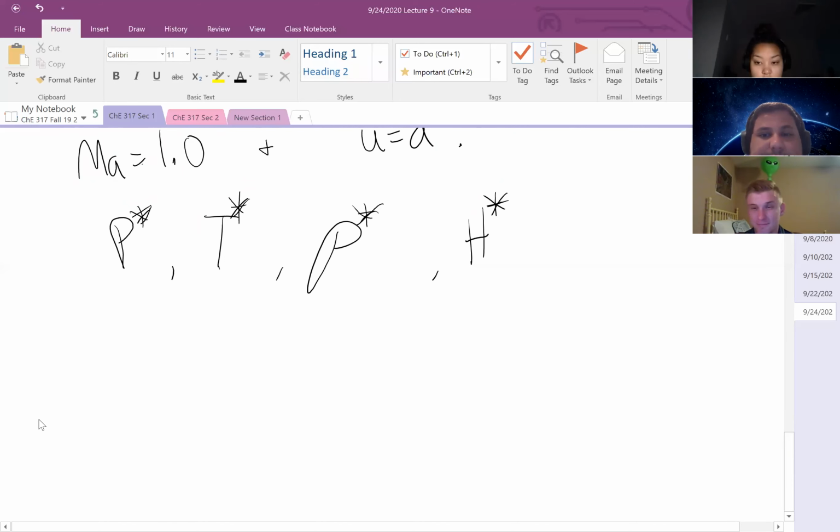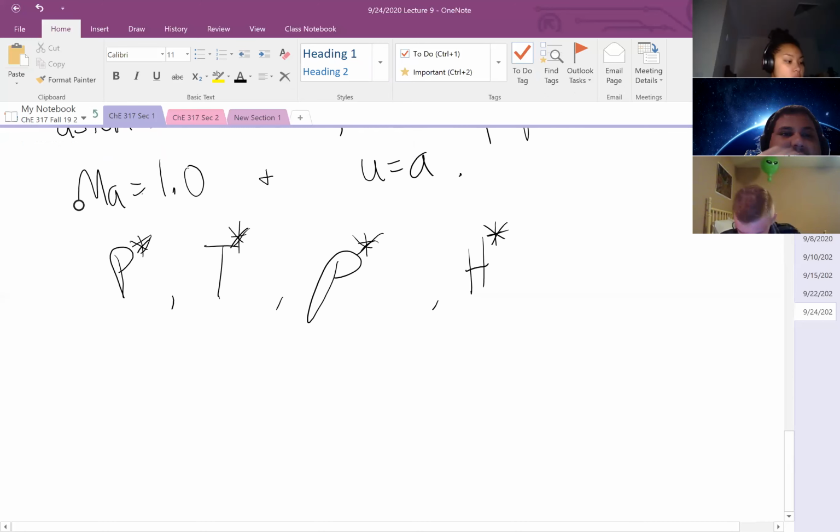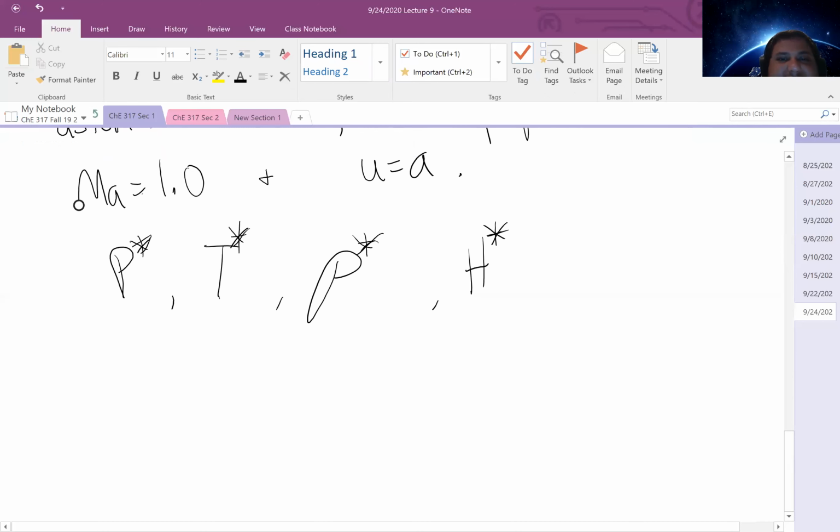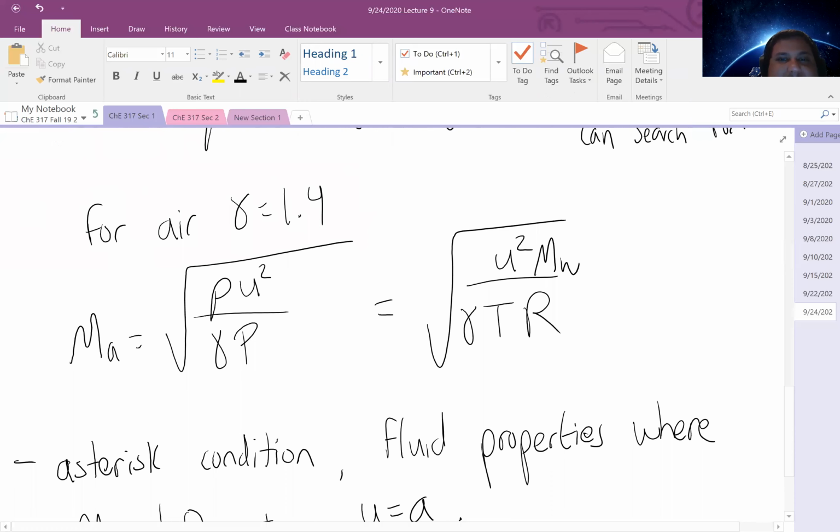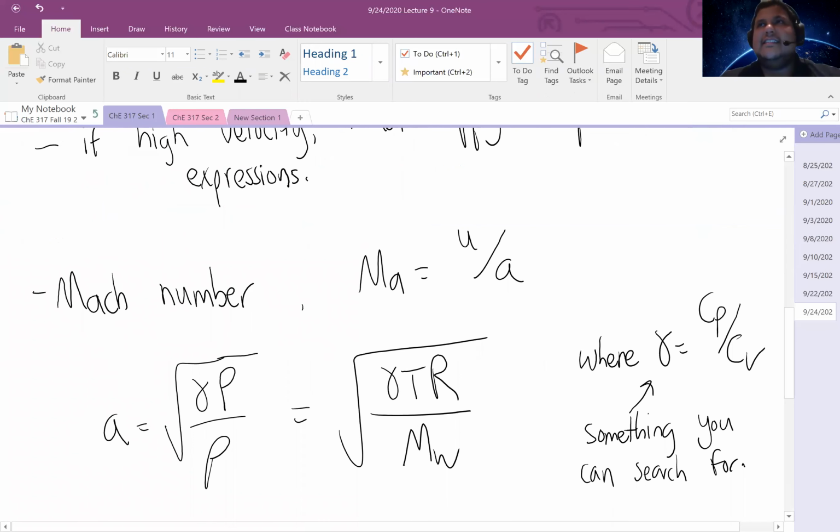I have a quick question. When you say high versus low velocity, is that just quantified by the Mach number to determine whether it's high enough or low enough? Yeah, that's a good question. I hesitate to give a rule of thumb because it can really depend on the situation. Let's say you have a really low Mach number in a system, but you could also have a very high flow length such that by the end of your system, you have an appreciably high Mach number.